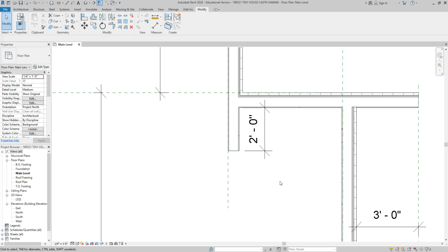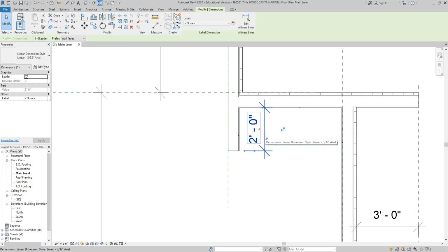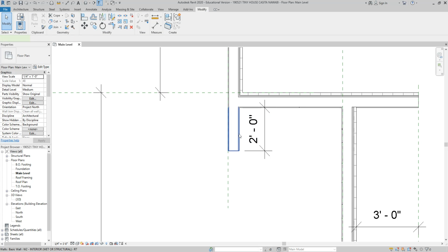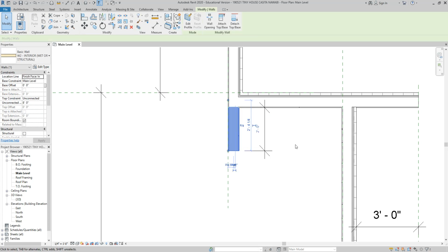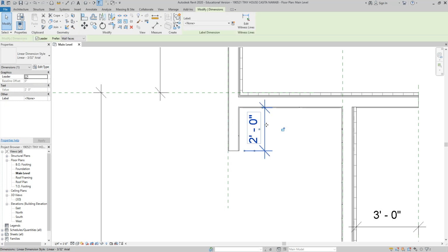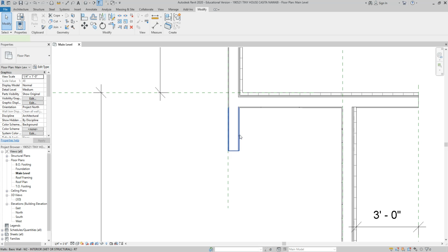Okay. Was it your reference plane, and you tried to change it? Maybe. Because mine was doing that, where I was trying to change the dimension of my reference plane to like 7'4" for the kitchen, and it kept going to like 7'2" or something, and I'm like, okay, I'm changing it, why isn't it doing it? Yeah, I just deleted it and redrew my reference plane and then redrew a dimension. Okay. And it was fine.